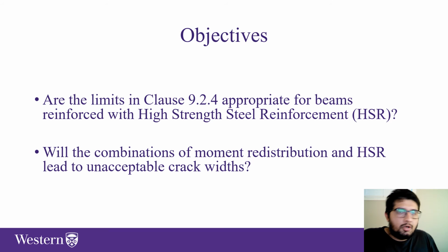So overall, the total objectives are: are the limits in clause 9.2.4 appropriate for beams reinforced with high strength steel, and will the combination of moment redistribution and high strength reinforcement lead to unacceptable crack widths?